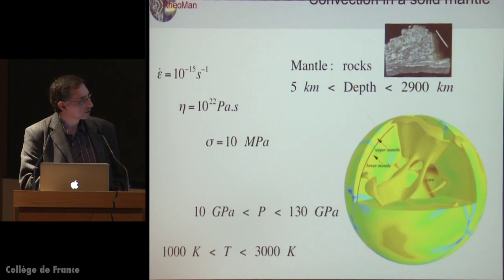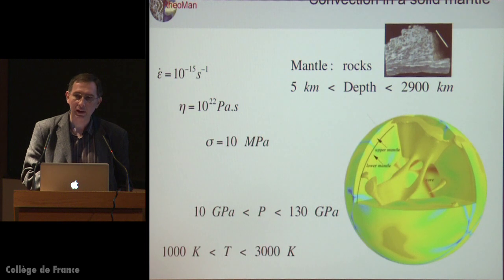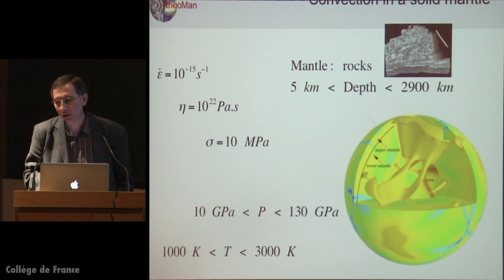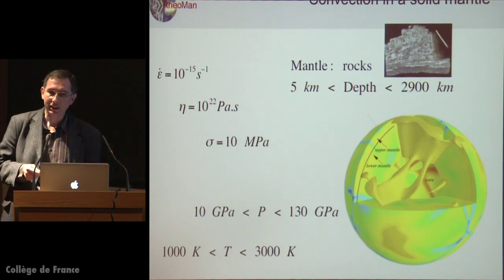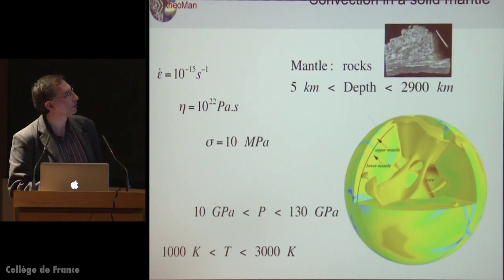Look at the figures here: this pressure exceeds 100 GPa, and if you think about the elastic constants of those minerals, we are within the same order of magnitude, which means that we can expect pressure to change profoundly the atomic structure or the electronic structure of those materials, so we really need to take this parameter into account at the small scale.